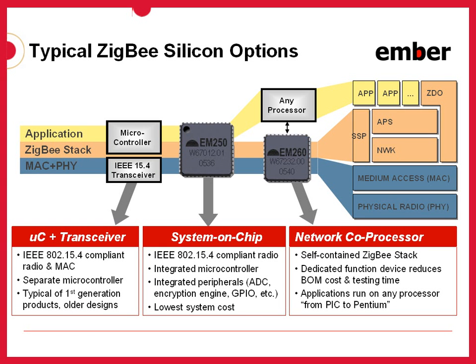The second model of ZigBee design here is the system-on-chip, or SoC design. In the SoC model, all stack layers, as well as the application, are implemented on a single chip, with lower-level stack functions often implemented in hardware as peripherals of the microcontroller. Like the two-chip model discussed previously, the access to stack functionality here is generally provided as library API calls. There may be a certain amount of shared access to peripherals or resources of the microcontroller between the stack and application. While this sharing may place more constraints on the application developer, it ultimately leads to the lowest bill of materials cost among the three models discussed here, and it typically offers the most compact hardware design of the three.